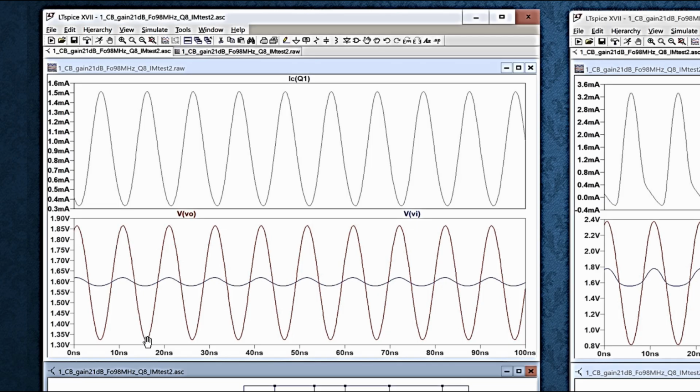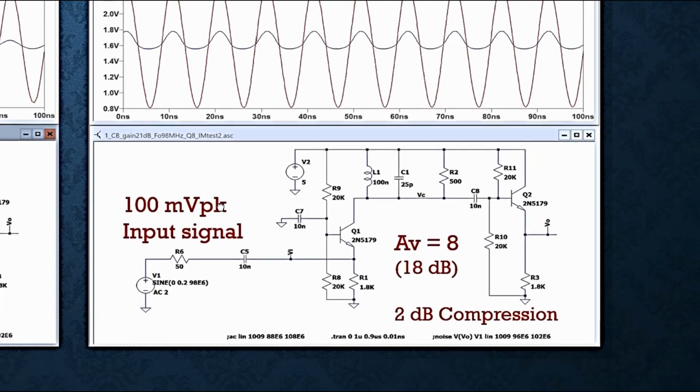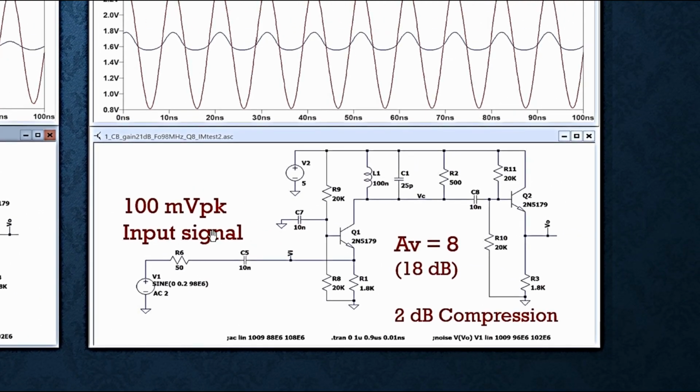So at least eyeballing, I don't know, look at this. This looks a little soft down here, this looks a little peaky. But let's find out what happens when we increase the signal to 100 millivolts peak. Well, you can see what happens. The waveform is now distorted, which if you remember some Fourier theory, you would recognize that that means that there's probably some harmonics going on.